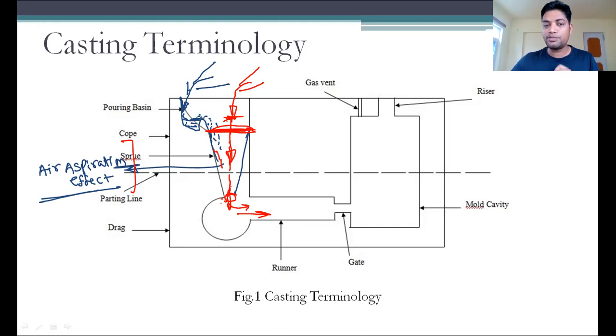Now, there is another reason for the cross section area being reduced. You are filling this molten material by using this sprue, so we have provided some specific mass flow rate or volume flow rate, we can say. So if it is coming with a higher flow rate than whatever is required over here, then it will start depositing over here.